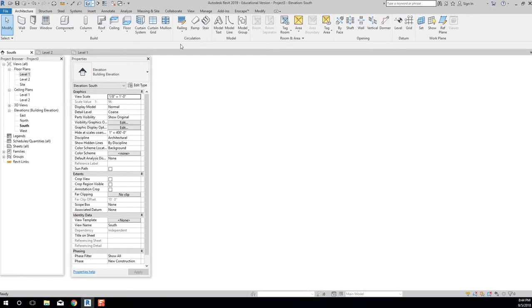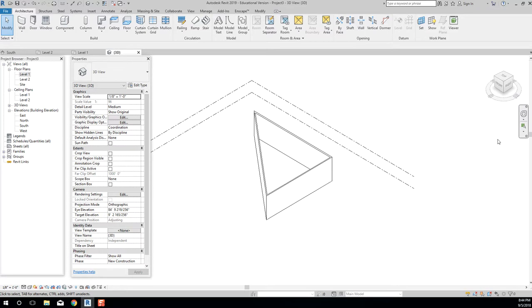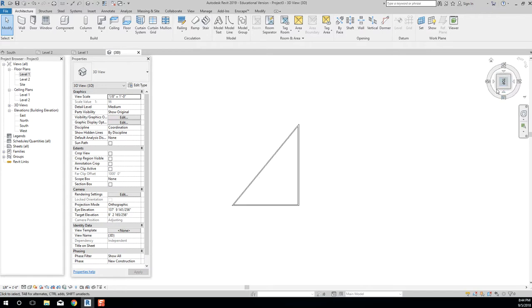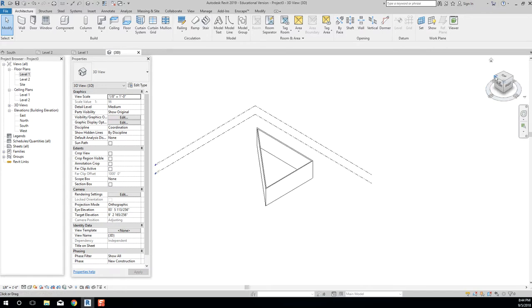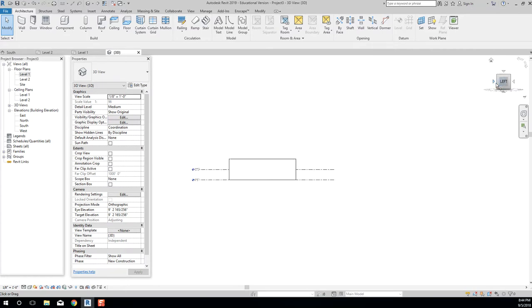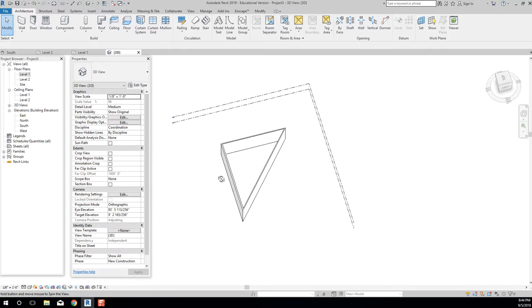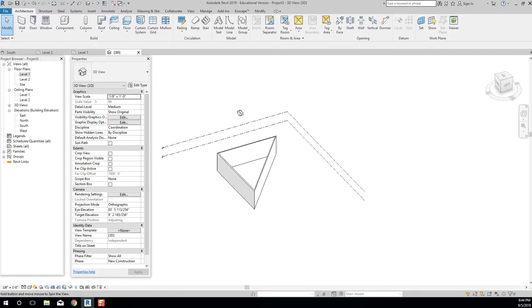If I'm in 3D, my view cube looks like this, right? This is a little bit more AutoCAD-looking. And if I click on the corner, back to 3D, right? So this is somewhat useful. I don't use it a whole lot because I'm more accustomed to just coming up here to 3D, click, and then, when I'm in 3D, if I hold shift down and hold my middle roller button down at the same time and move my mouse, I can orbit, right?